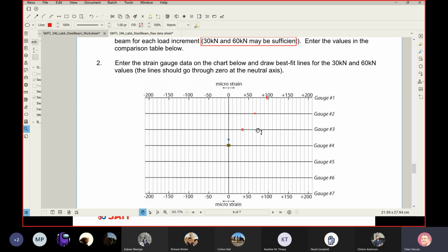Let's say 2. I'm asking you, what do you anticipate if I connect these points together? Does it give me a parabola or line or what? Should be a line. And that's exactly what the beam theory said. The beam theory says that when you apply bending moment, your planes will rotate in a linear fashion.